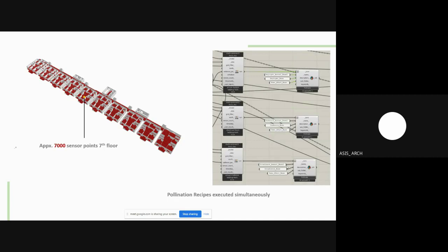All the Radiance-based simulations are possible at a pre-design stage because we don't need a single line diagram model. But if you come to the energy simulation aspect of ArchiCAD, that still lacks a ready-made design philosophy to convert into a single line diagram. So a lot of times as consultants, we start our design process with Radiance-based simulations using ArchiCAD, because it is directly interoperable between the interfaces.